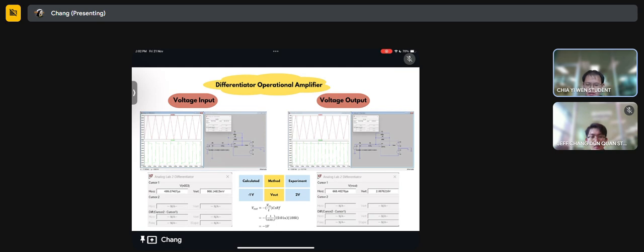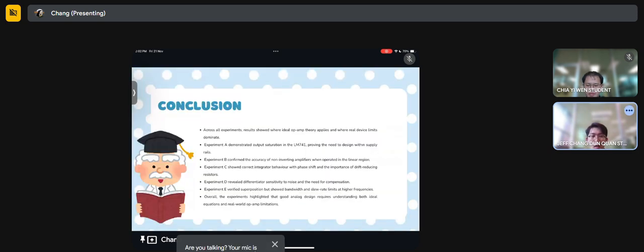Now I will pass it to Jeff. Okay, thank you, Chia. Now I will continue to the conclusions. Overall, the experiments show that ideal op-amp theory holds only in the linear region, once limited by voltage swing, bandwidth, noise, or slew rate, the real LM741's behavior dominates. This highlights the importance of balancing theory with real-world op-amp constraints in analog design.